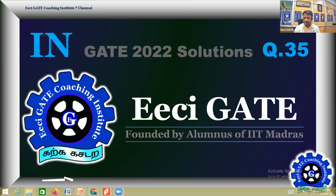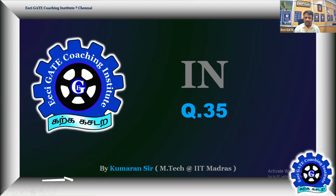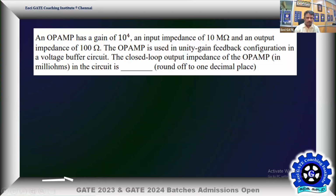Next problem, question number 35, another analog electronics problem, simpler compared to the problems I have done today. So this one you are familiar with. What we have is an op amp. It's not an ideal op amp; it has a gain of 10 power 4, an input impedance of 10 megaohm and an output impedance of 100 ohms. This op amp is used in the unity gain feedback configuration as a voltage buffer. You know what exactly the equivalent circuit is. Then the closed loop output impedance of the op amp in the circuit is?